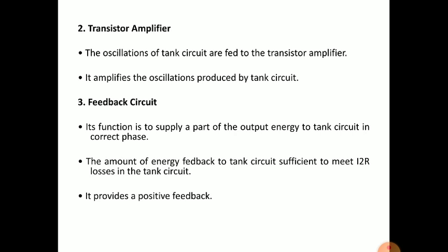It should be in phase signal because the output of an oscillator should be a continuous waveform. There should not be any out of phase signals after one cycle. The phase should not change. It should be in phase, then it will be a smooth, continuous waveform with oscillations with a particular time period, frequency. All those things will come into effect. So whatever feedback circuit we are designing in this oscillator circuit should produce an in phase signal with the